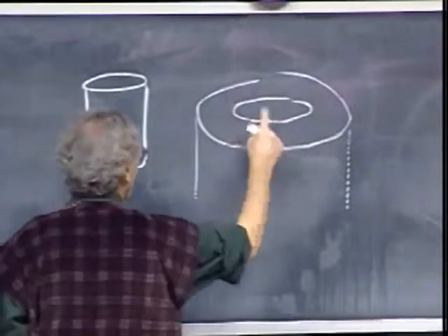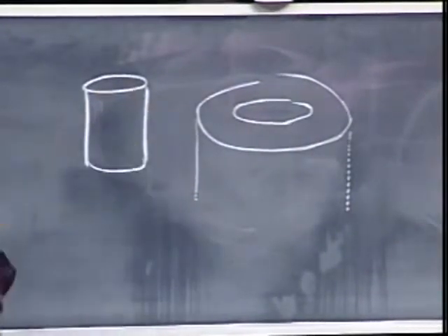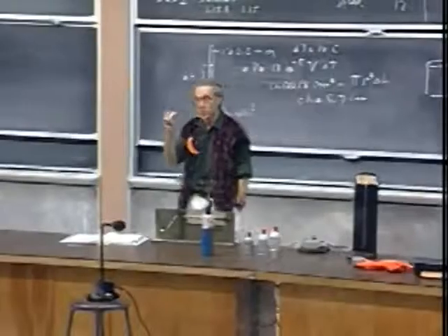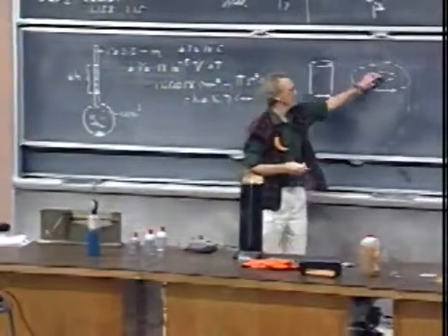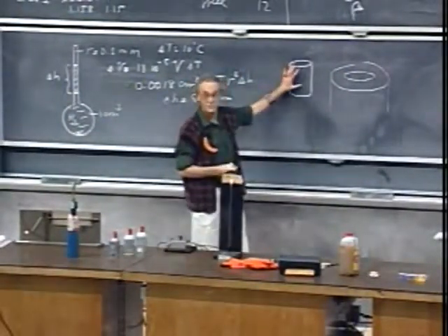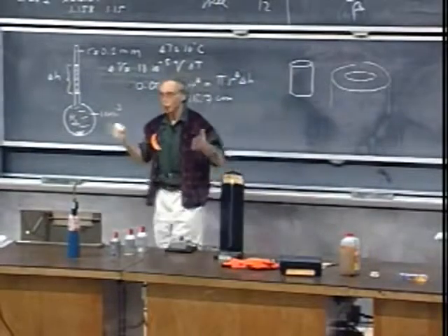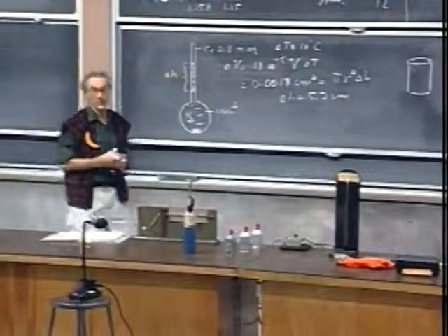Now this one, this opening, is smaller than this. Just a little smaller. Purposely made that way. You heat this one, it expands, and then you put it over here, it will fit, and then you let it sit, it cools, and it tightens itself up. That's called shrink fitting, a technique which is often used.